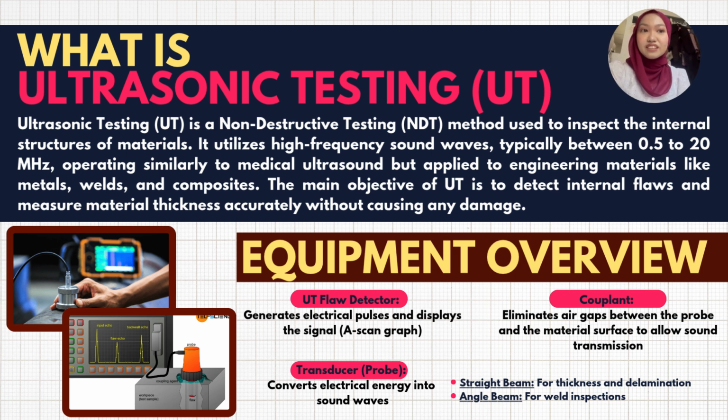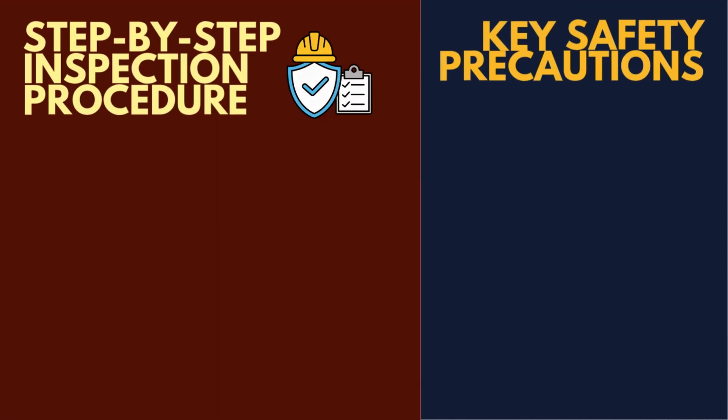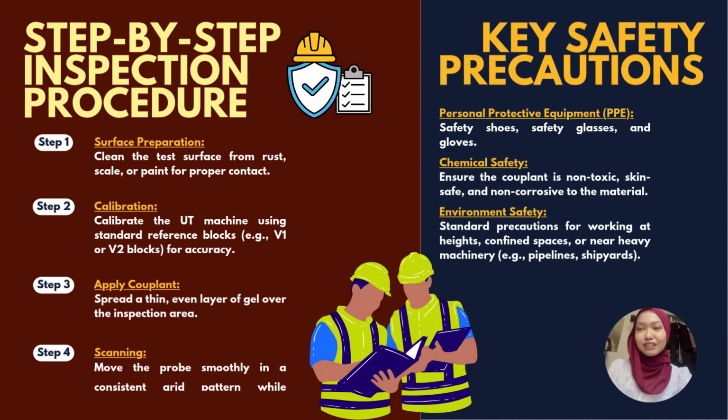The third one is couplant. It eliminates air gaps between the probe and the material surface to allow sound transmission. Next, we are moving to the step-by-step inspection procedure.